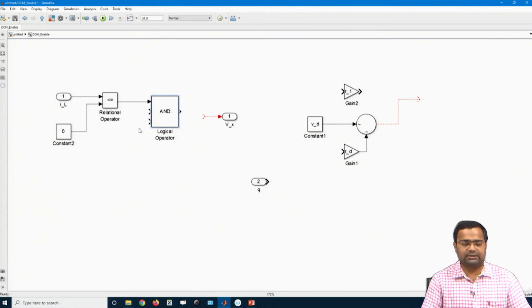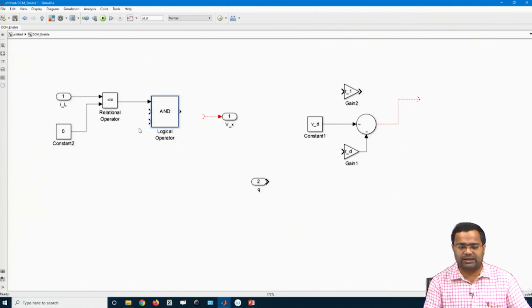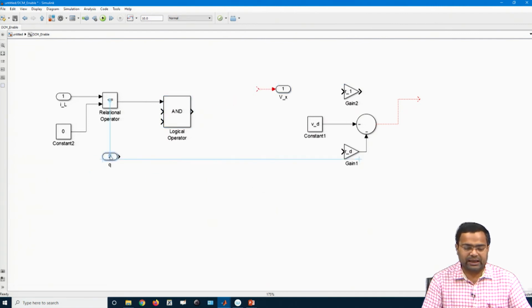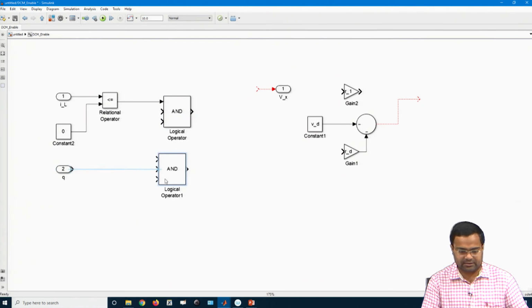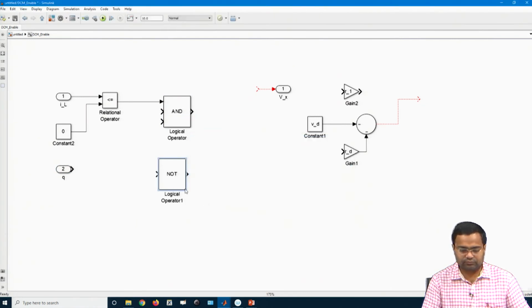We have discussed that this 0 detection circuit output is one of the inputs to the AND gate. Then what is the other input? The inverted logic of the switching signal. That means we can create another NOT gate, a smaller size NOT gate.